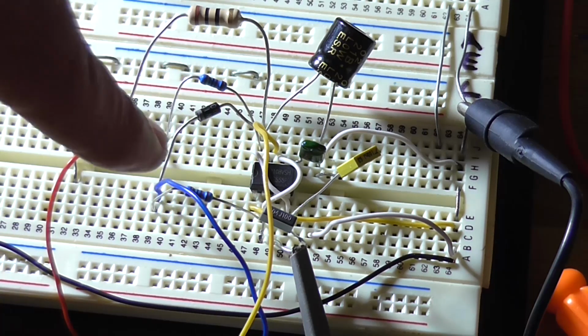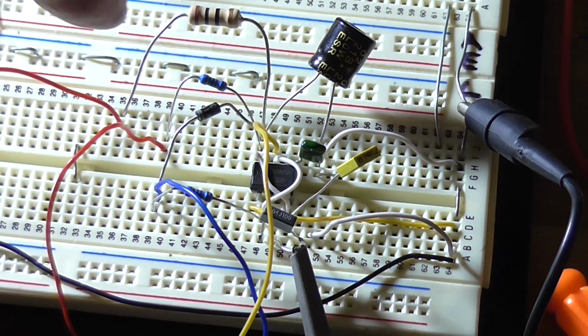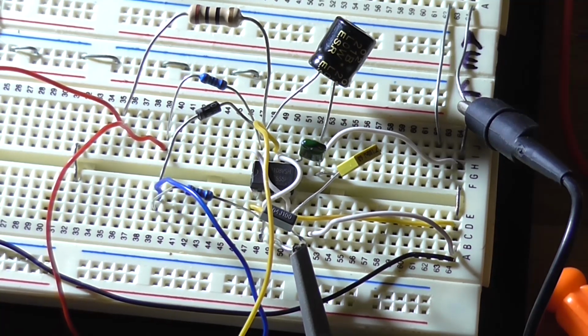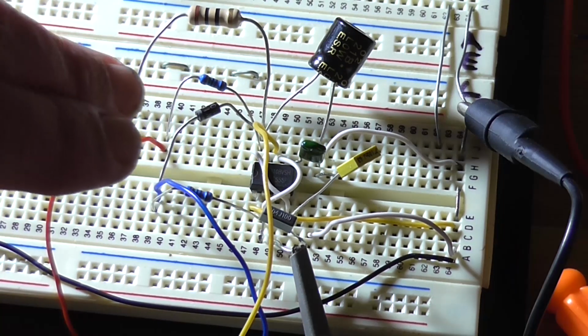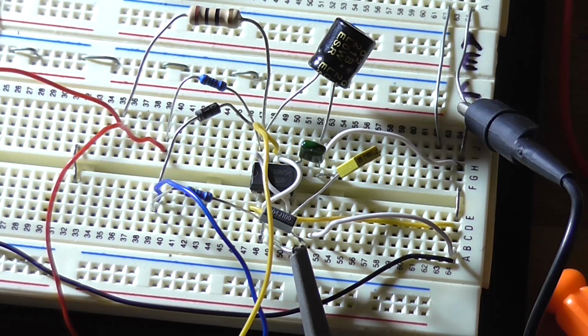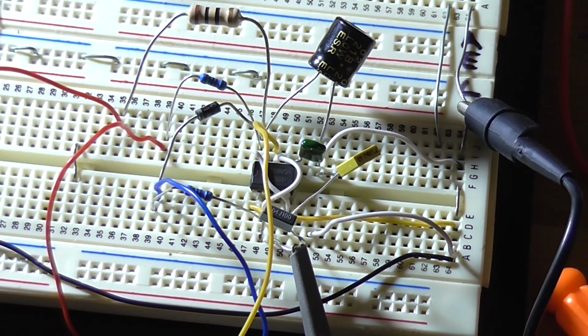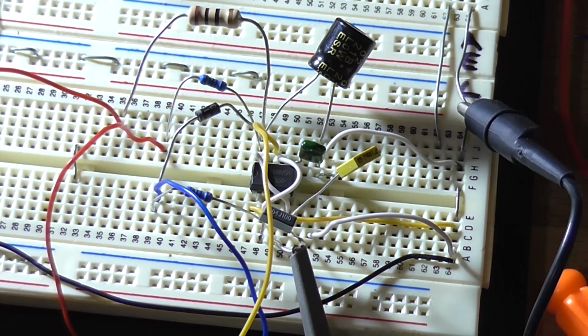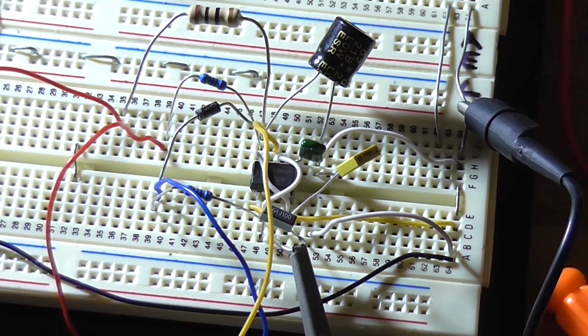If you change the resistor value between the positive and, say, discharge, and you have a greater resistance between discharge and threshold, you're going to change the duty cycle as well as modify the frequency slightly. I actually initially thought that the frequency would be varying, but no, it's the duty cycle. Oh well. Next thing to do is to build an output stage so we can actually connect it to a motor and see what it does.